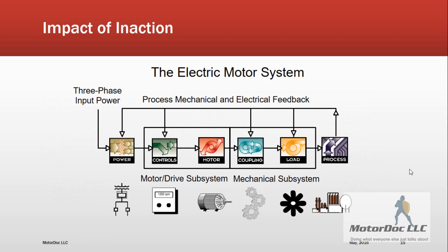The impact of these concepts can be tremendous. What if we need to determine if a system can operate 24/7 for the entire year, skipping a shutdown? We're building a case for the application of machine monitoring, diagnostics, and management has made the decision that maintenance is not required because the machine does not fail that much. We look back at the history of the machine components from the control to the load and determine the following. The motor starter has failed once every 15,000 hours. The motor has a good history and has failed every 25,000 hours. The coupling fails every 12,000 hours, and the driven load fails every 20,000 hours.